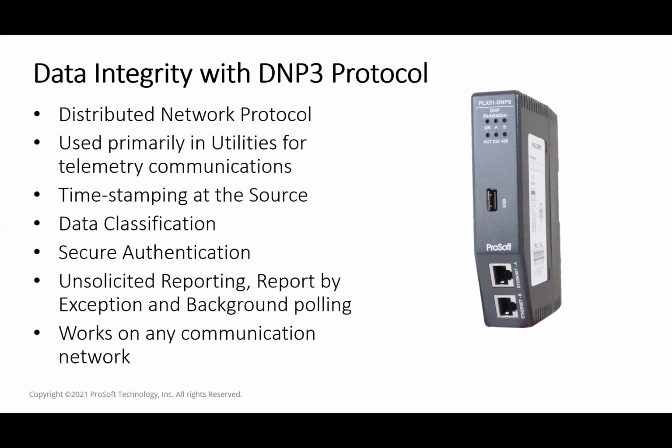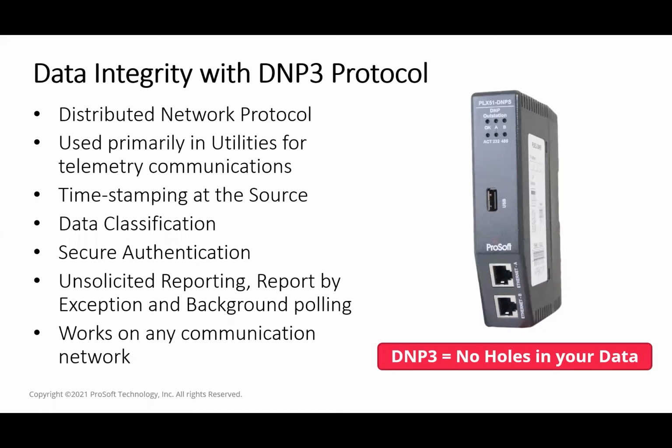We are not going to have time to cover all of it today. If you do need more information or you want to have a better understanding, please get in touch with your local ProSoft manager or your distributor, and we can certainly help you there. But basically, at a very, very high level, what DNP3 allows you to do is to make sure that there's no holes in your data, because it allows you to classify your data and it logs the data, meaning it stores the occurrence of an event, whether it is good or bad, whether there's an alarm or a standard event, with a timestamp that's local to the site.